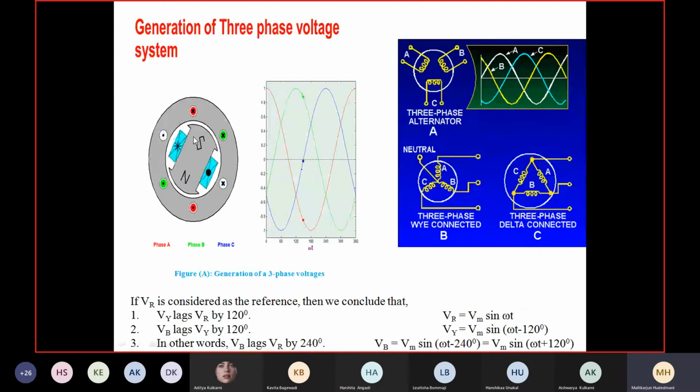So this rotating field mechanism makes an induction of EMF. Those induced waves are plotted in this manner. If it is a symmetric machine, we will be having Vm sin omega t, Vm sin(omega t minus 120), Vm sin(omega t minus 240), symmetric in dimension. Dimensions are symmetric and there is a phase difference between beginning of first, second, third systematically by 120 degree. That is what we have to see. Generation of three phase AC takes place by rotating field mechanism, group of magnetic poles and group of conductors incorporated here.